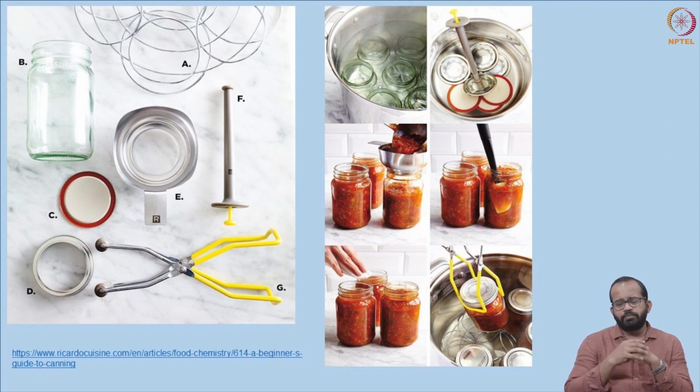Another type of glass is borosilicate, in which 5 to 15 percent boron trioxide, B2O3, is added. The main property of borosilicate glass is its high thermal resistance. Lab glassware and glass used for thermal processing are made with borosilicate. Another material is alumina silicate, where 5 to 10 percent aluminum oxide, or alumina, is added.